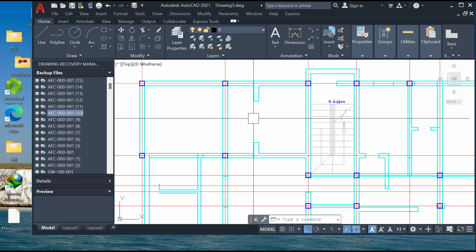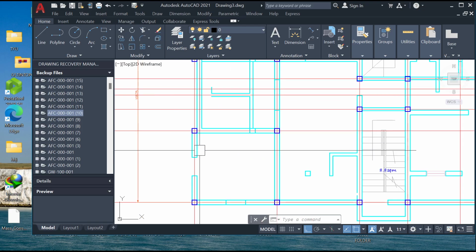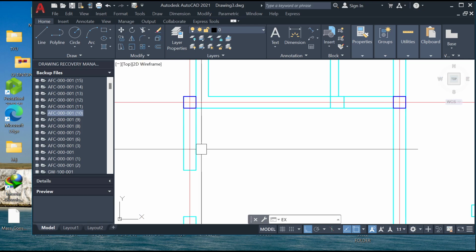That's one. Two, you might need to increase the section of the slab, because what we intend to use is a 150 slab. So you might need to increase the slab thickness to maybe 175 or 200 so it can pass. Or you might need to increase the reinforcement, so it will not make the design economical. So that is why I take it as a rule of thumb to make sure that my slab panel does not exceed 30 square meter.